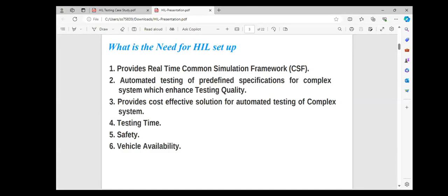By using the HIL automation tester, if we start execution one time, it continues for whatever time is required, be it 24 hours, 48 hours, 72 hours, 3 days, 4 days, 5 days, with an uninterrupted mechanism. It will continue to execute all the test cases, and we can call it a night run.